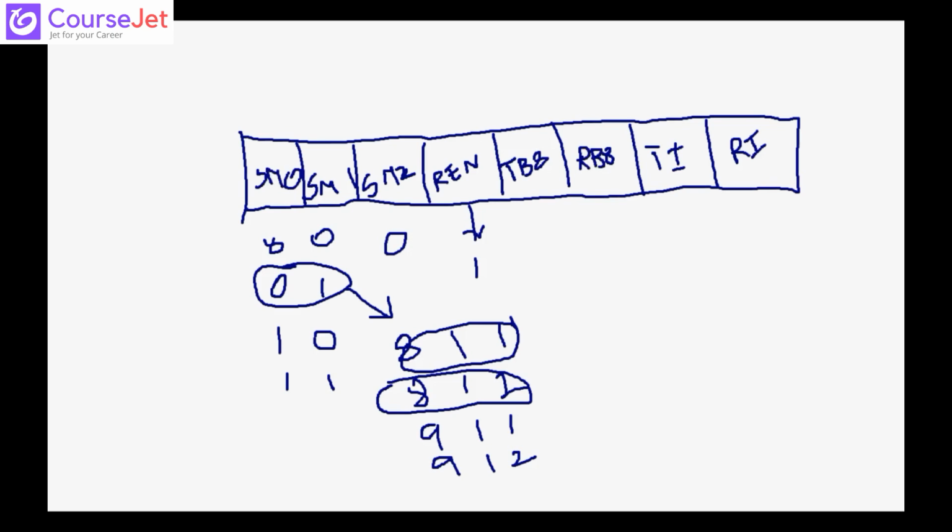Suppose I am using 9 bits of data. As I said, we transmit and receive data in the SBUF register. SBUF register is of 8 bits. If I want 9 bits of data, where will that 9th bit go?